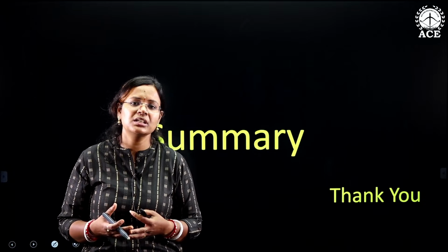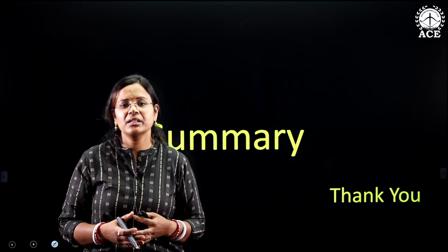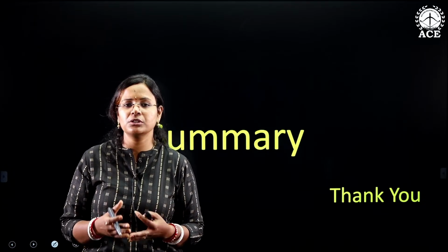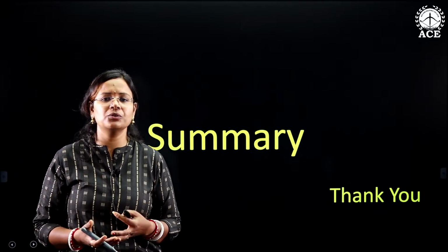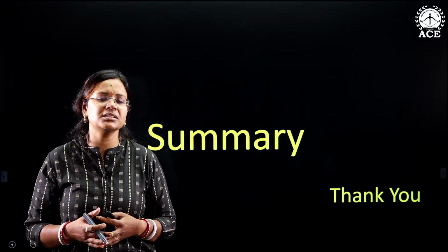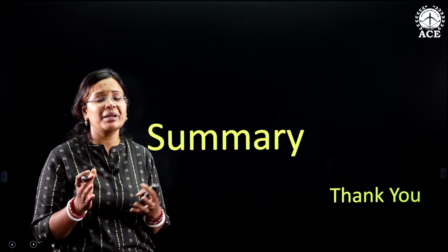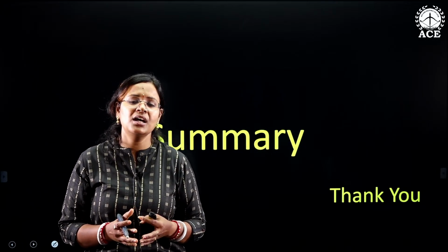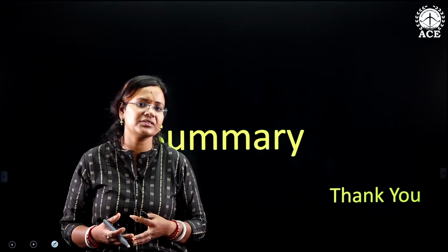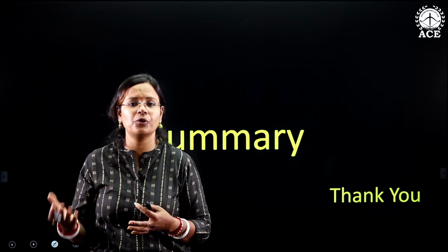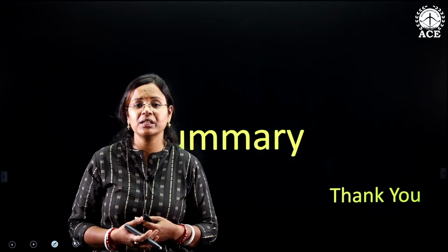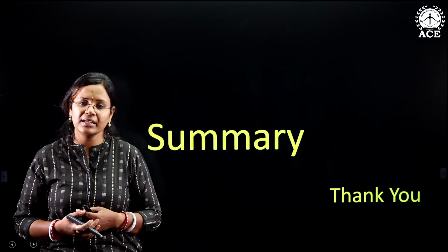Classification of followers: knife edge followers, roller followers, flat faced followers, inline followers, offset followers. The major part of this session was the construction of the cam profile, where the stroke is given and the different motion of the follower is given, and based on that, how we are able to construct the cam profile.